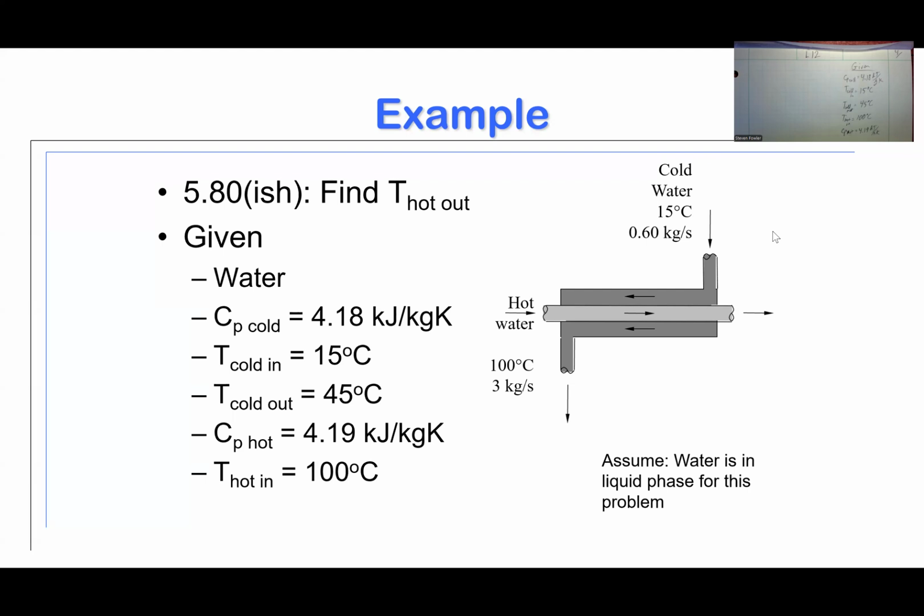So this is a heat exchanger problem, and I just want to reread that. A thin-walled, double-pipe, counterflow heat exchanger, which really is just telling you adjective, adjective, adjective heat exchanger. It's thin-walled because you're going to have a very, very thin separation between the hot stream and the cold stream right here. It's counterflow, meaning that the outer stream is going to flow in one direction and the inner stream is going to flow in the other direction.